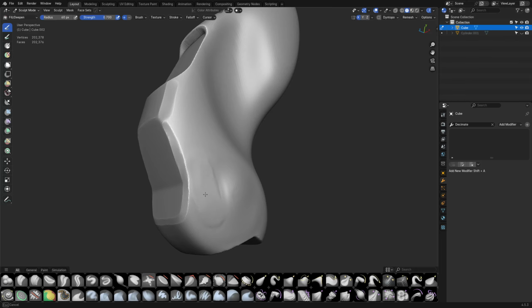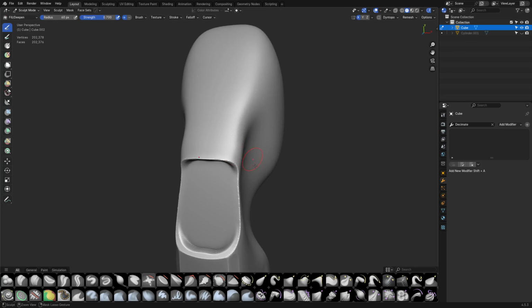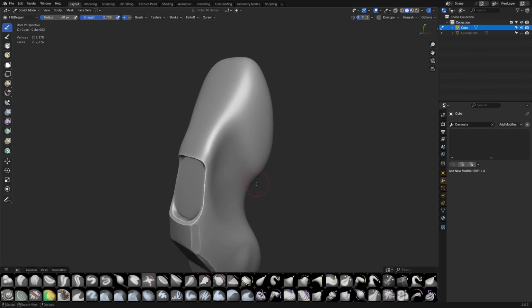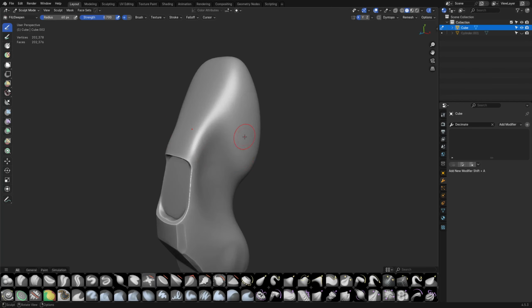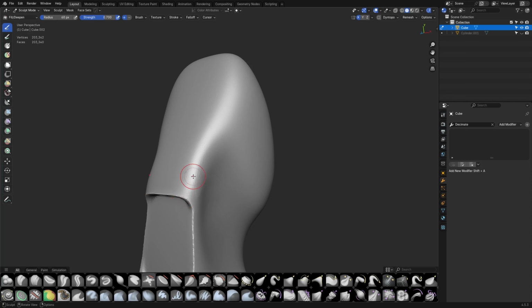These should be able to be worked as a blockout piece, or basically you can start constructing really complex looking objects using dozens, if not hundreds of different parts and pieces. Using meshes like this, they don't have to be more dense than this, right? 200,000 is pretty high already. You can actually even leave them much lower than that. It really wouldn't matter. The only time you want to go higher resolution is when you're trying to turn them into quads and you're going to use some kind of automated system like Quad Remesher, right? And even that doesn't work out perfect. Otherwise, you're going to retopo these kinds of things and turn them into quads that way.